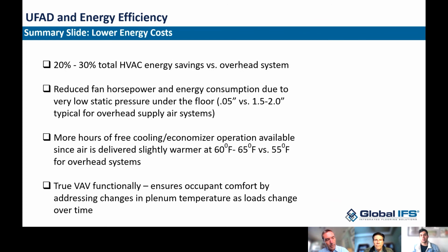ASHRAE, that is the first thing that they'll tell you is to increase your outside air. Makes all kinds of sense in terms of what they call their ventilation rate procedure, which basically is a way to quantify the cleaner air story in a building. The thinking is, the more you can flush outside air through the building, the better. Now, for the most part, it applies really well, especially in places like where you are, Chris, and you are, Braxton, in Denver. But if you're sitting next to the 405 freeway in California, that may not be such